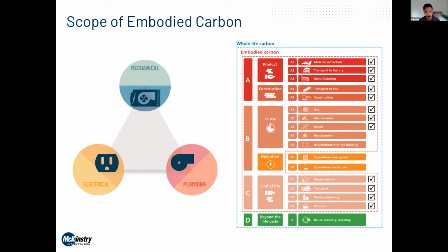The other thing I wanted to talk about is just what LCA stages you're including when doing embodied carbon calcs. So typically, I think when doing ILFI embodied carbon calculations, you're including A1 through A5 of the embodied carbon. For MEP components, it can be a challenge to get all of those things. So I'll go over an estimating methodology developed by CIBSE in a little bit called TM65. But yeah, just trying to include everything that's in that embodied carbon life cycle stage.